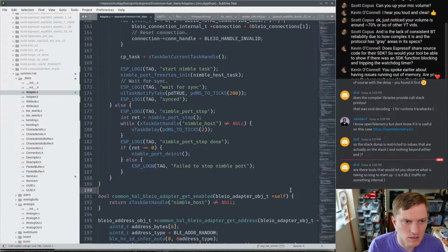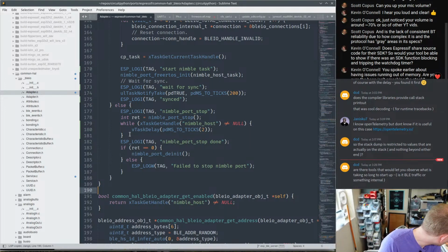The other thing I could do is I might have UART output. I don't have headers on this feather, but I might actually have debug UART output on the RX and TX pins. So I could add a separate UART. That's probably not a bad idea, especially because I'm having issues.